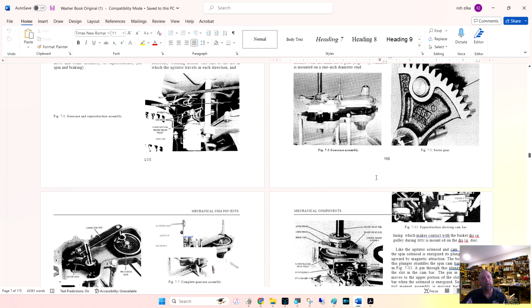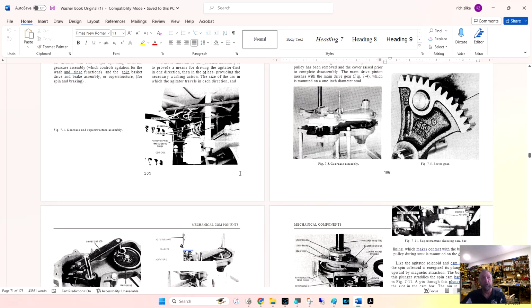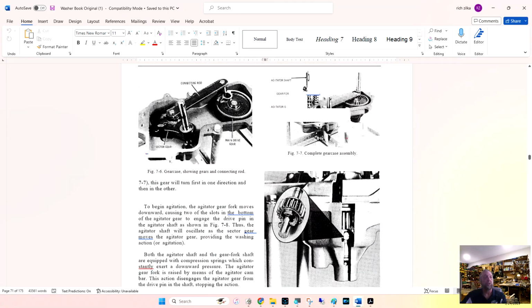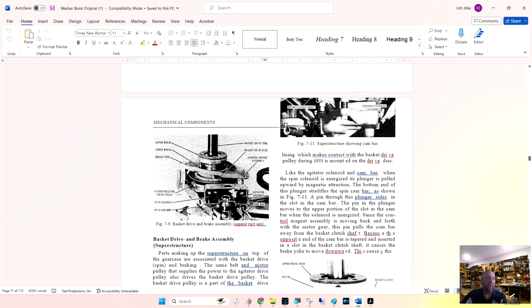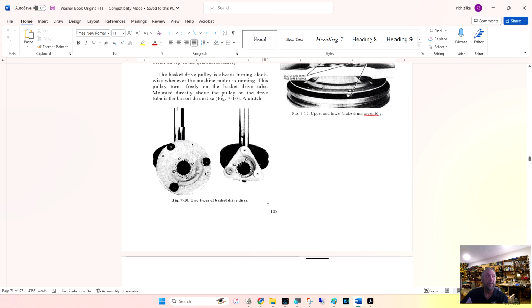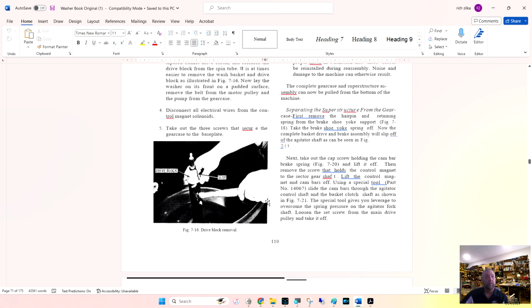This here, we were talking about the transmission and brake mechanism, this is the old belt drive washer transmission. This thing was a beast. But just to show you, the bottom half is the brake mechanism and the upper half is the clutching mechanism. Well, actually, vice versa. Clutch is this plate and this pulley, and the brake mechanism is this pad and this pad where it squeezes it and it stops the machine from running. So this is a mechanical brake and it didn't have a locking mechanism. It had its own braking mechanism.